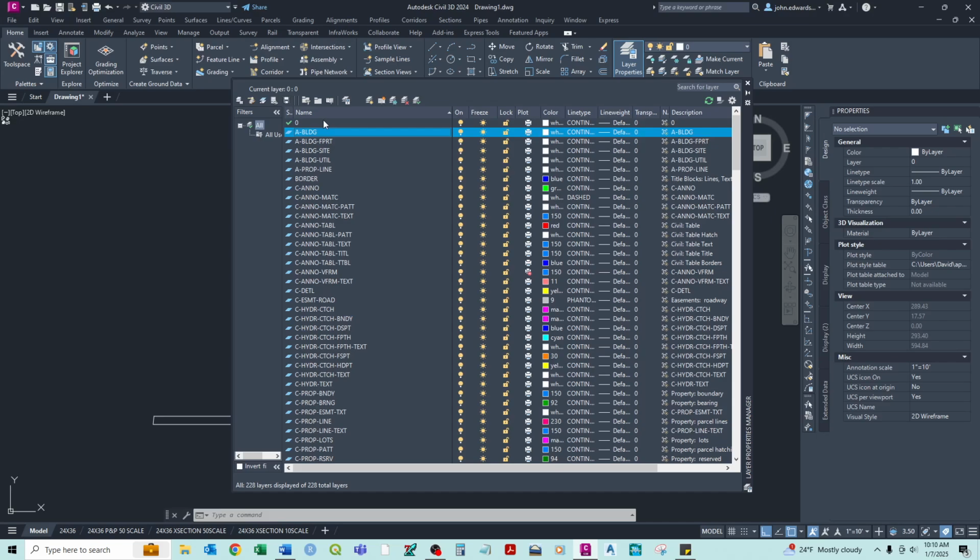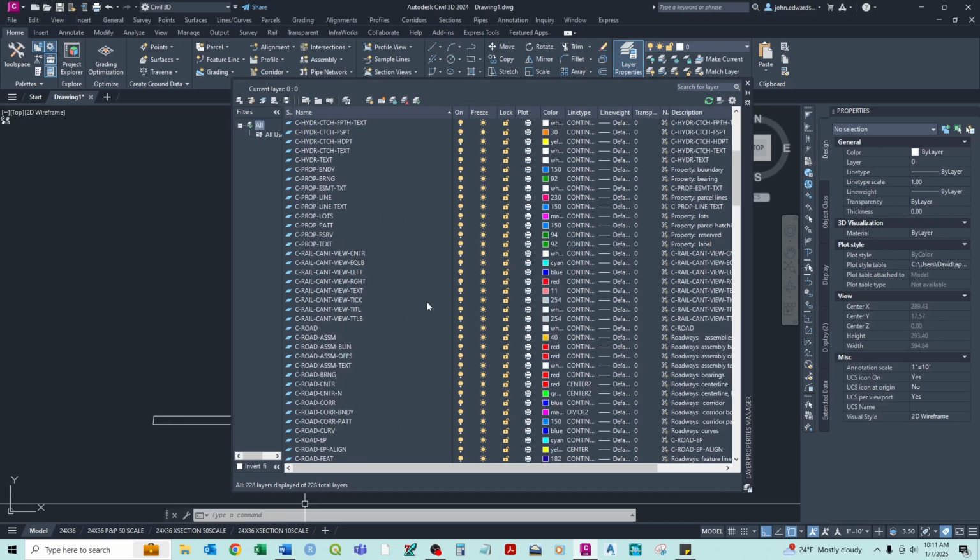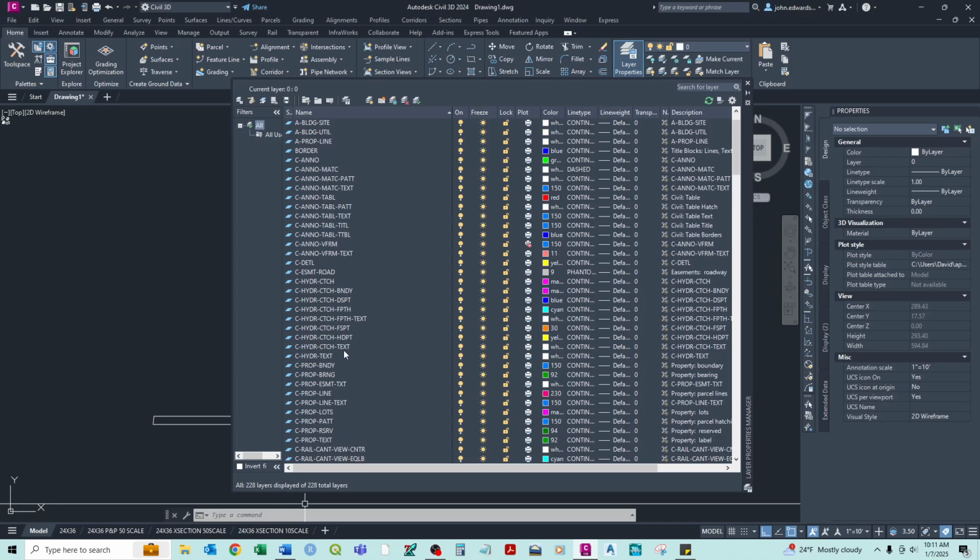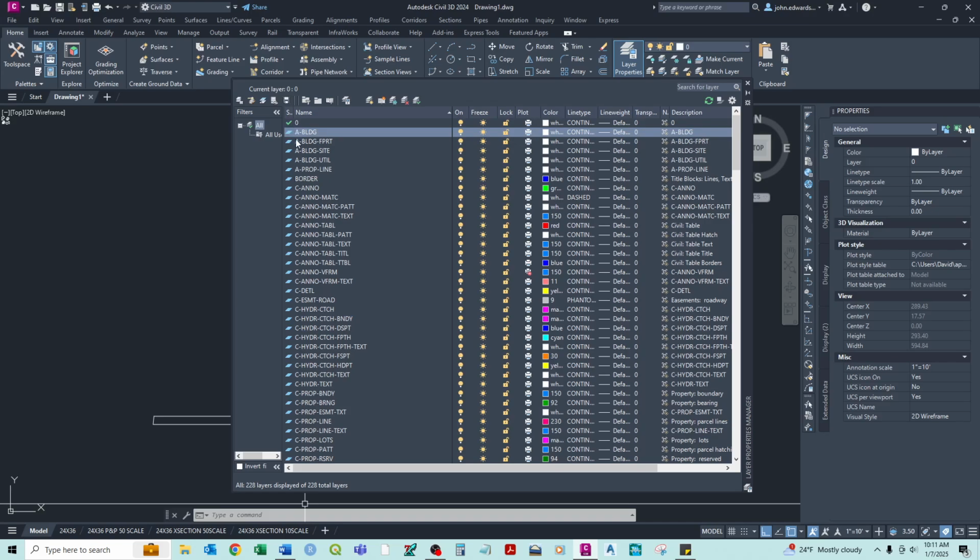Essentially, one is going to be a scratch layer, and I generally call that construction lines. And then another one I always create is a 2D line work. These are the things you need to manually draw in, but they're going to stay in the final plans. And because I'm kind of lazy and I don't like searching all the way through here, and it's essentially alphabetical but numerical first, when I create new layers, especially ones I'm using a lot, you come up here and there's this little sunshine next to the papers, new layers, or you can use Alt N.